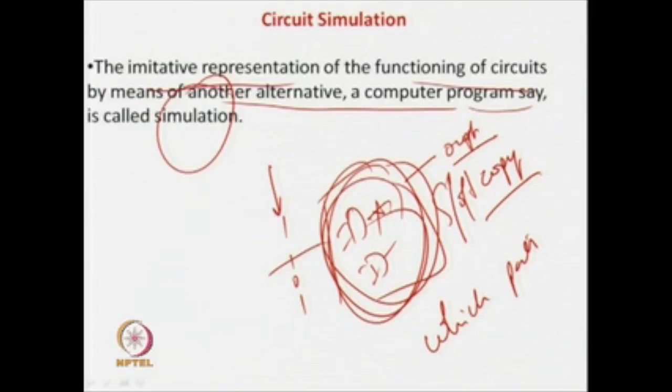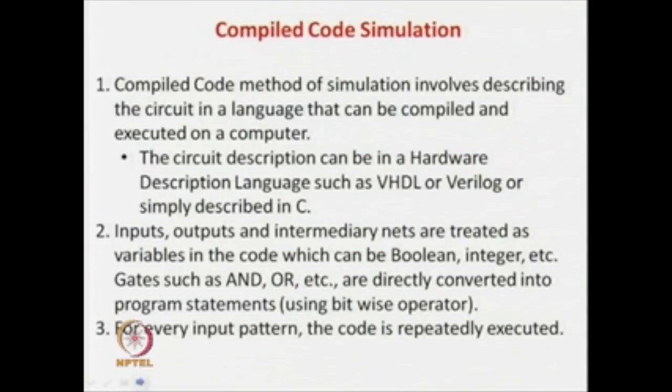That is very much required for fault test pattern generation by the sensitize, propagate and justify approach. So, we will study in detail circuit simulation and also fault simulation. What do you mean by fault simulation? In fault simulation, the circuit is there as a program, a fault is inserted in the circuit represented as a program, and you find out the output corresponding to a random input.